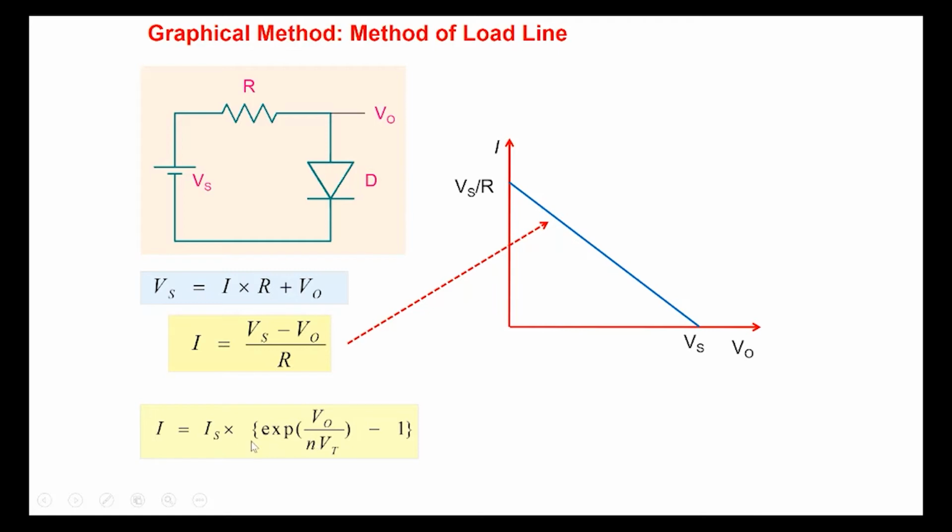And then plot the diode equation here. And wherever the two intersect, that's the solution. Right? So you take a circuit. We said analyzing a circuit is nothing but transforming a circuit into a set of equations. And solving those equations when they're nonlinear, you could do that by plotting them together on the same pair of axes, and wherever you find intersection points, that would be the solution. So this point here is common to this equation, and this point is common to the diode equation here. So that's the solution of these two equations together.